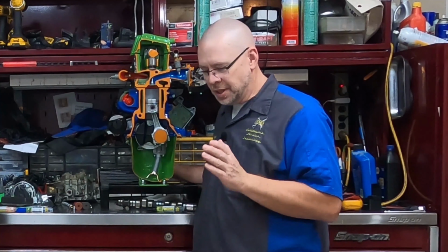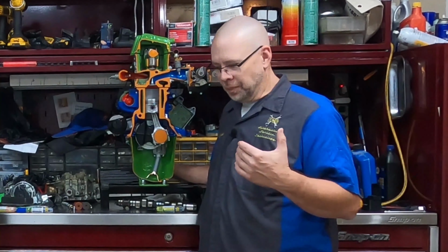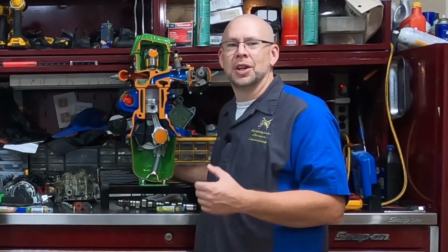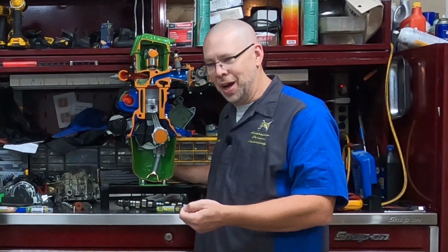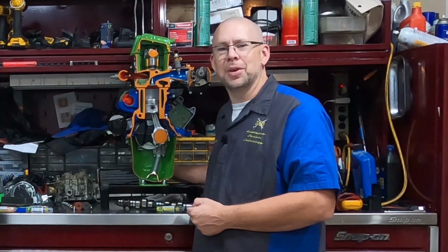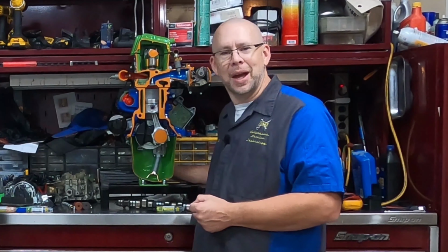When it comes to actually moving that timing, now everything's computer controlled. The PCM has a variety of factors it looks at: speed, position, load. We have some inputs specifically for timing. And it uses those to help determine the proper timing, but that's not how it started out. Back in the early days, say Model Ts and all those old cars, you actually set the timing yourself. There was a knob that you pulled out or pushed in on the dash to change the timing, and you manually set that timing as you drove the car. It had one setting to start, another while you were cruising. You moved that timing around manually.